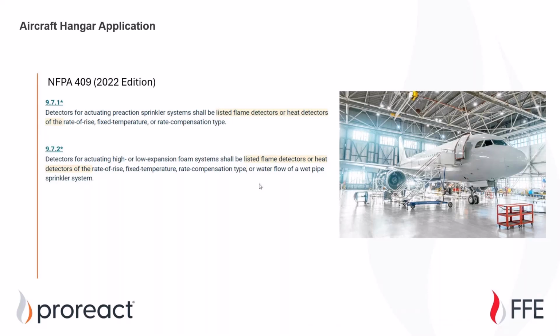But in that study that they had done of over 30 years of foam deluge dumps, it was found that most of those incidents, there were a few hundred incidents, were caused by false alarms, and the only fatalities that had occurred were from false alarm foam deluge dumps, and not actual fire scenarios. So a lot of that is also in development with flame detectors and linear heat detectors very much in the conversation.